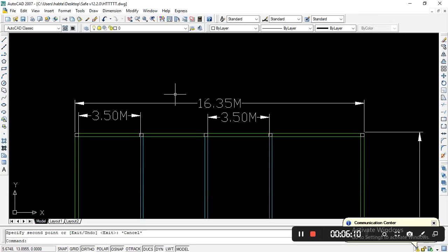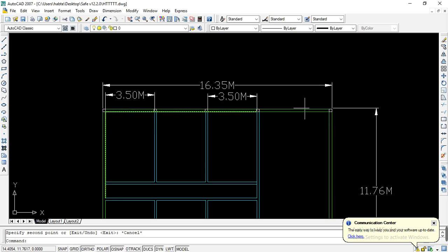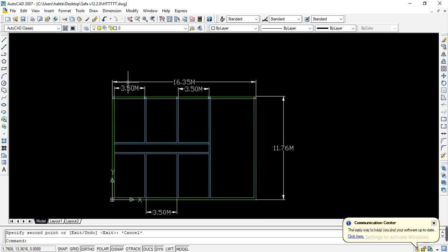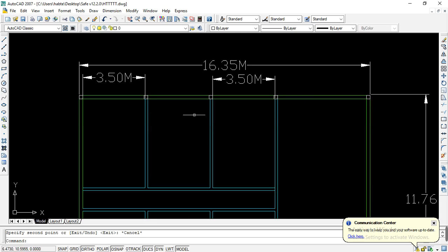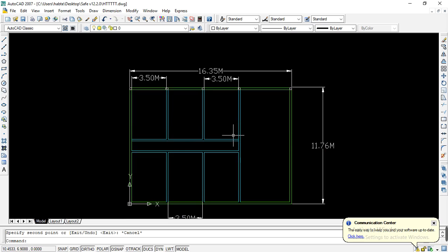The next thing that I'm going to do is insert the green lines or the grid lines in between those columns, and then select those columns with the grid lines. Then I'm copying or duplicating those five columns with their own grid lines to this and this one also.